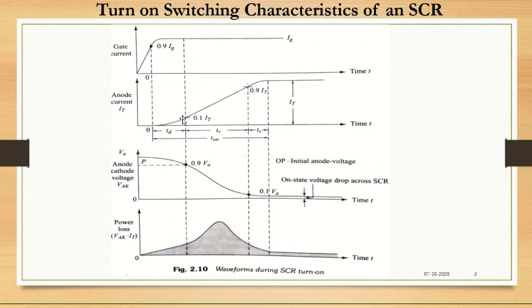So now you have to visualize the internal structure of the SCR device, right? When sufficient charges are injected by the gate terminal, they cause multiplication of charges inside the SCR device, which in turn eventually causes the current to flow through the device. Then you say that there is an increase in the current happening, correct? So this is our delay time.